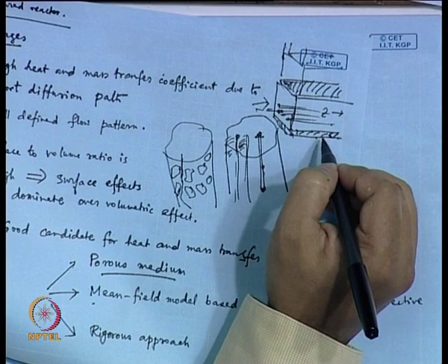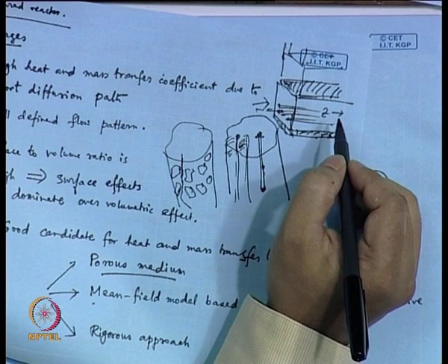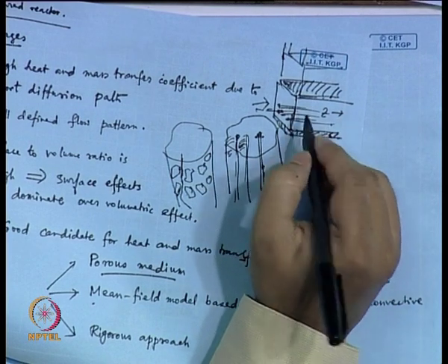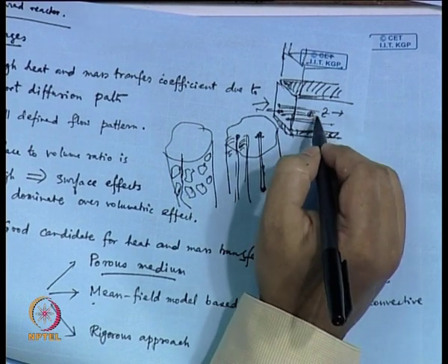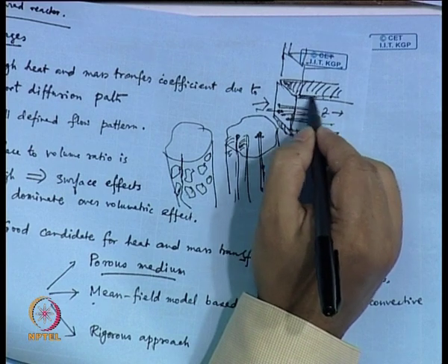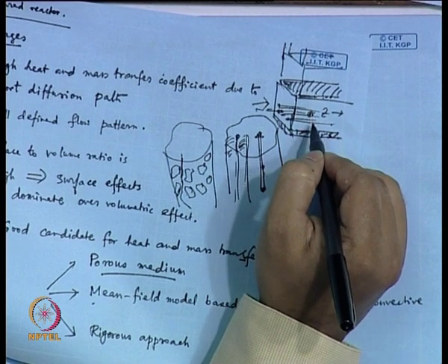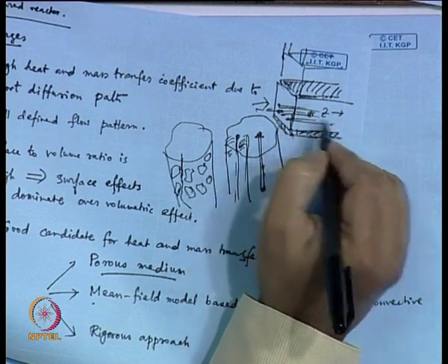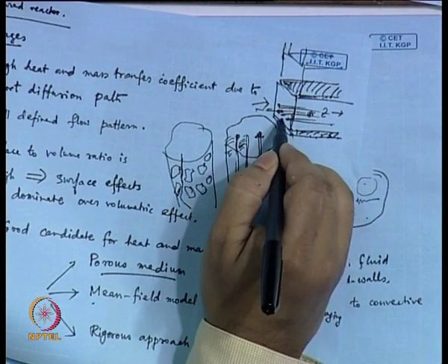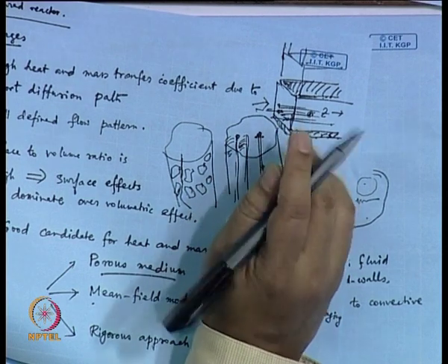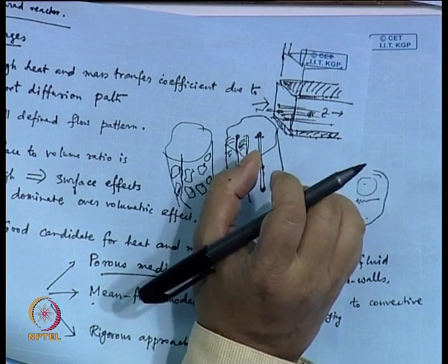So, you are having a hot fluid flowing through this, or by some other means you are heating this layer, all right. So, you have this heating layer here, this heating layer here, then which place would be the coldest within this block? It should be the center, right, by symmetry. So, this area would be the coldest, and here it would be the most heated. So, you can expect within this block there is a temperature profile. Now, this block has thousands or millions of channels, that is another issue, and the feed is flowing through this channel and taking the heat. When the gas is flowing through this channel, it is absorbing the heat, right.